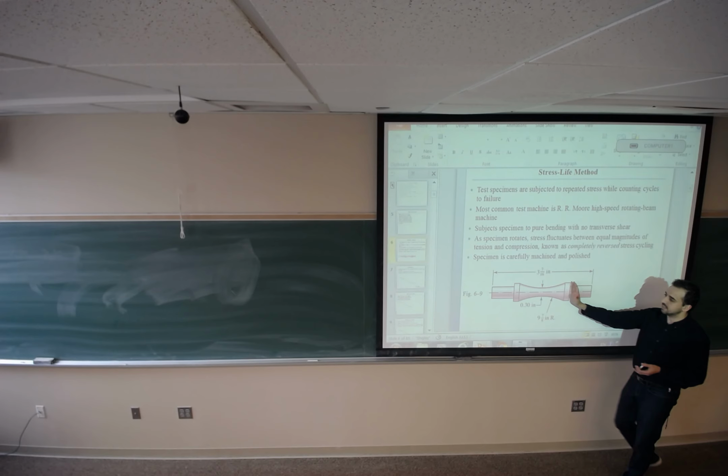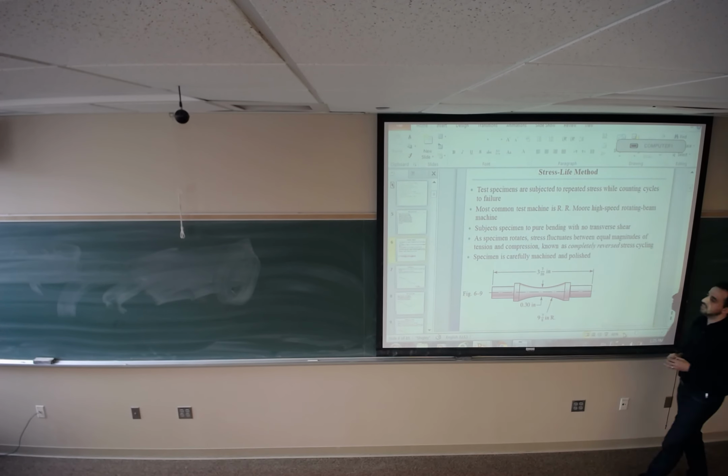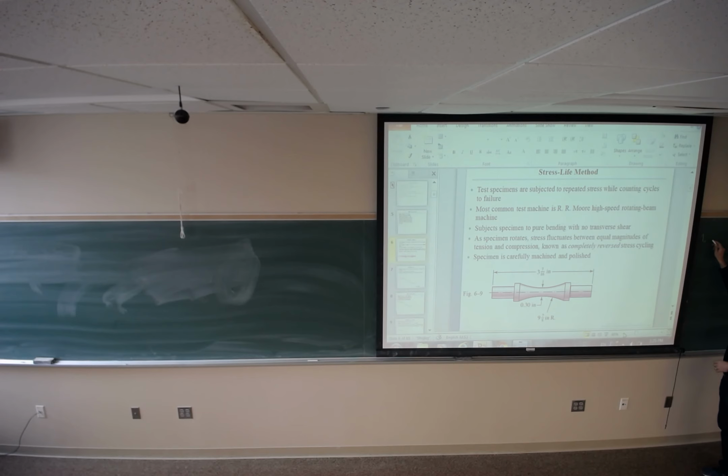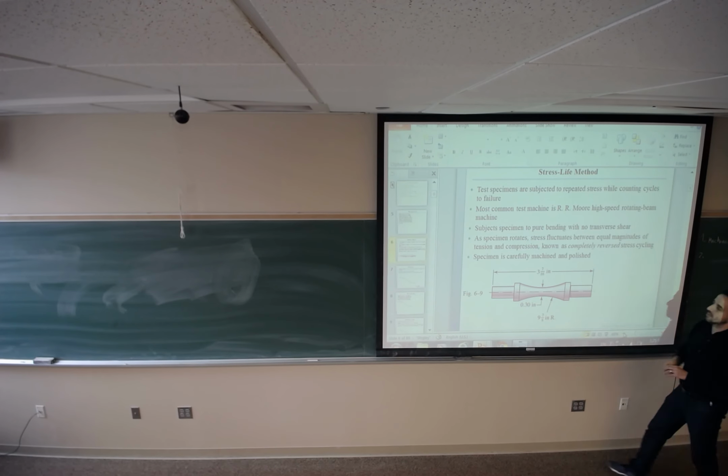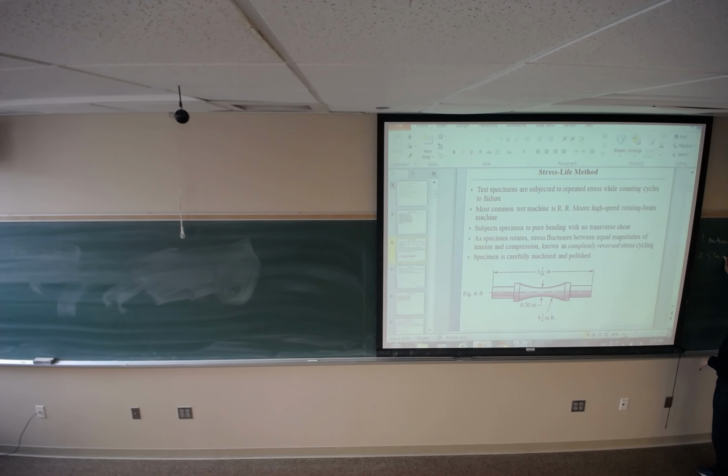So it's machined and polished. It has the standard dimension, and it's completely reversed bending moment, pure bending.